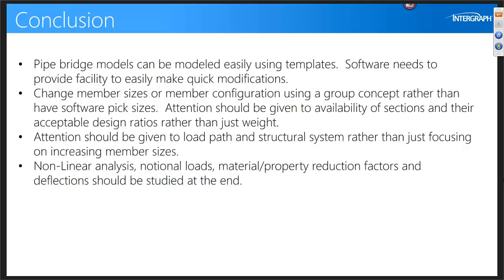The danger with that is, if you model a pipe inside GT Strudl, you're actually relying on the stiffness of the pipe. So the pipe is actually carrying the bridge, so that's the problem.